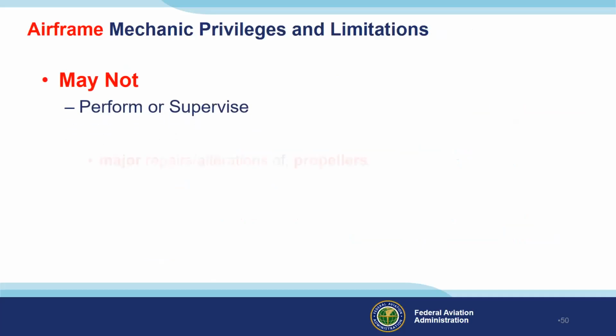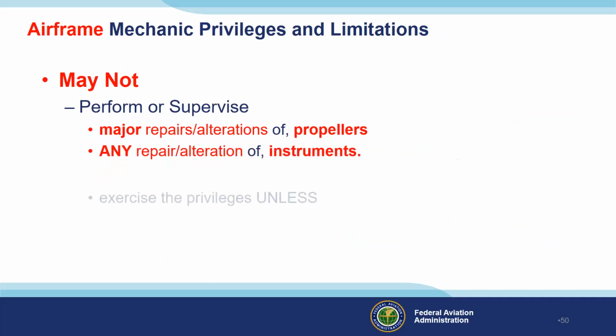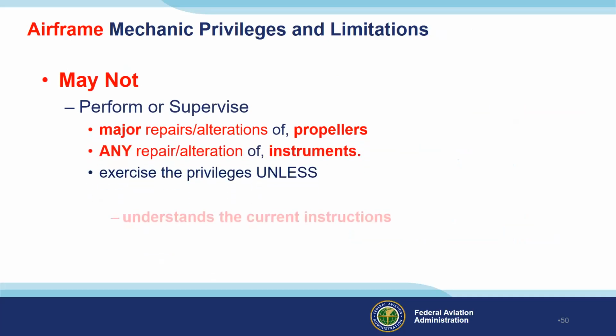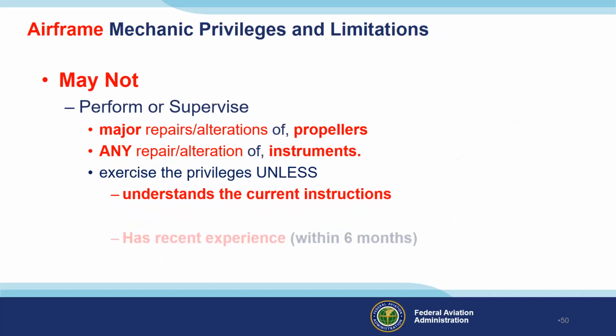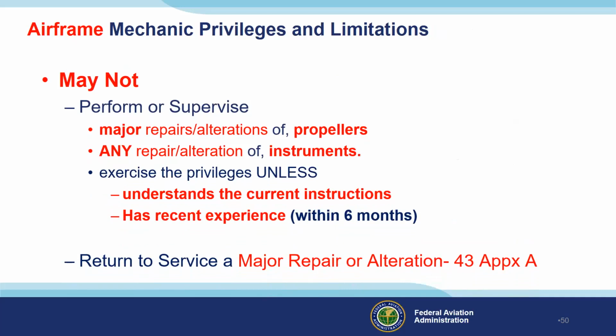You may not perform or supervise major repair or alteration of a propeller, any repair or alteration of an instrument, and you can't exercise the privilege unless you understand the current instructions and you have recent experience. And a lot of people forget about the recent experience requirement.